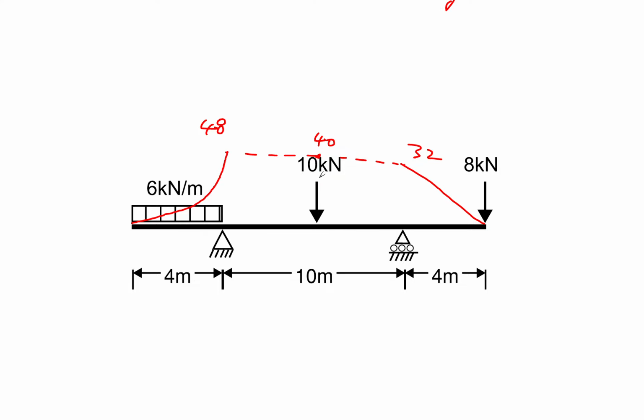And because at the middle of the span there's a point load, the moment acting at the midpoint is PL over 4. So the P is 10, L is 10, divided by 4 is 25. So it's a positive moment of 25. And there's a negative moment of 40, so they counteract each other. So negative 40 plus 25 gives negative 15. Let's say right here, straight line. So right here, that is a negative 15.